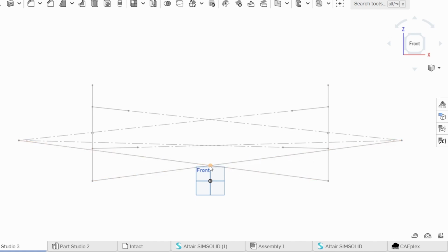As the suspension moves throughout its travel, the angles of the A-arms will change, and the instant center will move as well. And then you'll continue drawing the lines from the wheel center to the instant center, the dynamic point of them. So your roll center may or may not move as suspension travels.